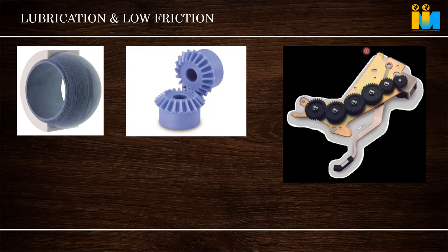I want a material with strength better than nylon, so we put some glass into it. With glass, the lubricating property reduces and friction increases. It heats up and becomes difficult. Then PTFE or some lubricating fluid additives are added to compensate, so the coefficient of friction will reduce. Go and see the data sheet of any lubricating grade that raw material makers position for lubricating or frictionless application. You can see the coefficient of friction given in it, and we have to see that and select.